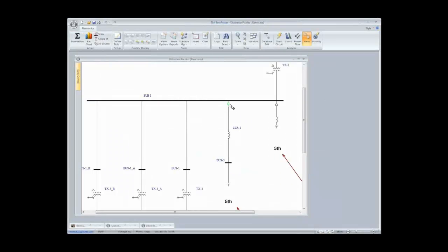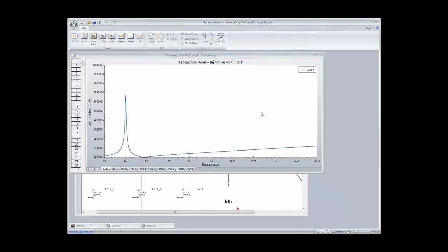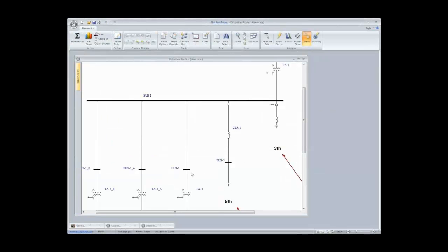And if I were to use this one, broken out into separate components, I get identically the same simulation, about the 4.8 harmonic sitting right on the third. So these two modes are completely comparable with each other. If you want to break it out into separate components, you can. If you want a single component, you can do that as well. In this case, if I do a summation calculation for my distortion, notice that I'm plotting root sum square voltage here.